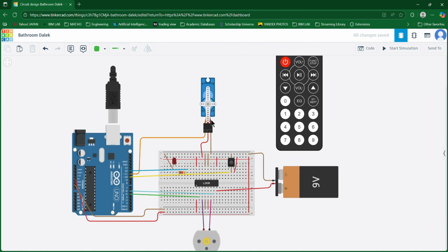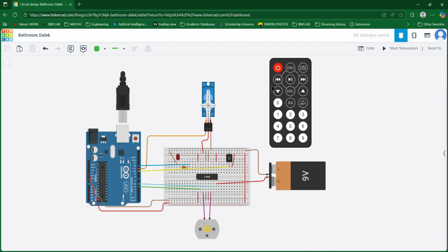So let's see how the fumigation process works. The servo motor is going to activate a chemical reaction to start the fumigation process, and 30 minutes after, the UVC light, which is actually the LED in this circuit, will turn on for 30 minutes. 30 minutes later, the servo motor will go back to its original position, the LED will turn off, and the DC motor connected to the motor driver will run for an hour. The IR circuit is just for the remote control itself.